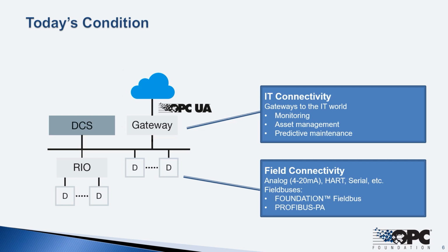A bit of a side note on HART devices. I remember a statistic shared by Ron Helson when he was still with the HART Communication Foundation. In fact, they even published this on their own website at one point, that over 80% of the HART installed base were not used to provide anything more than the basic 4 to 20 milliamp signal. In other words, not many of these users felt the need to access the HART channel or the HART diagnostics.